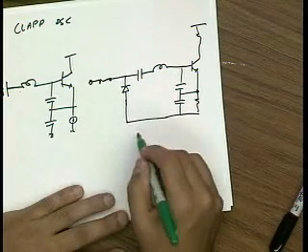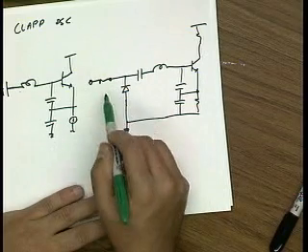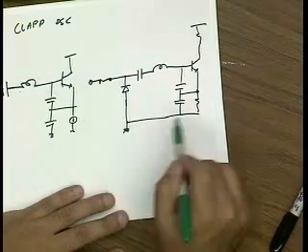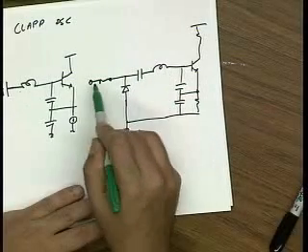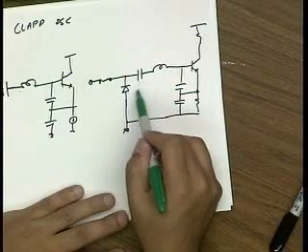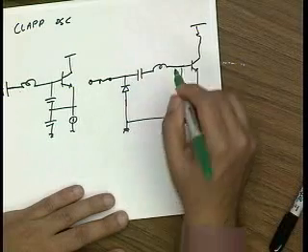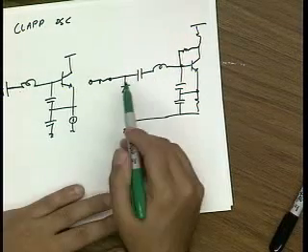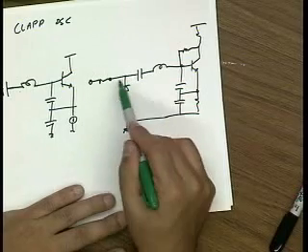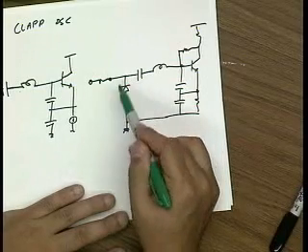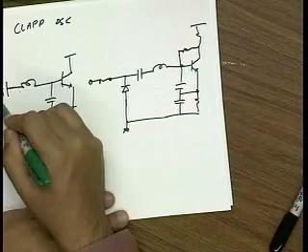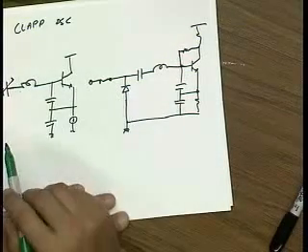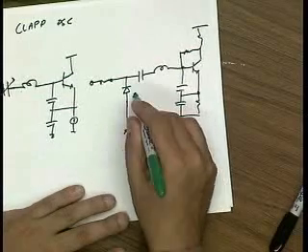Because the DC point here will not disturb this circuit, I can vary this DC value because I have this cap isolation. So maybe I have a large resistor or something like that to bias this up. Now I can change this DC value, which will change the capacitance here. So this becomes a variable capacitor, and that will change the resonant frequency of my tank, and so I get a VCO.